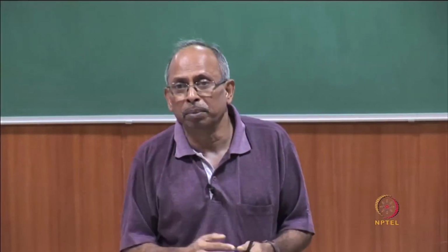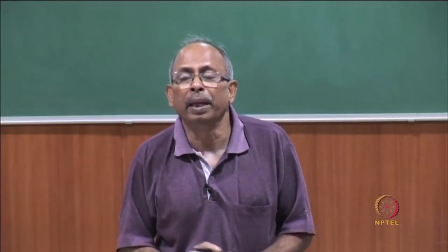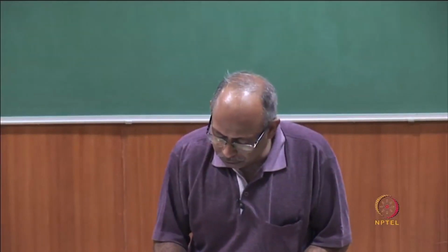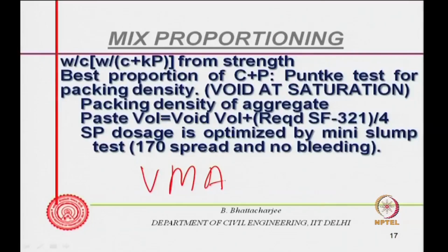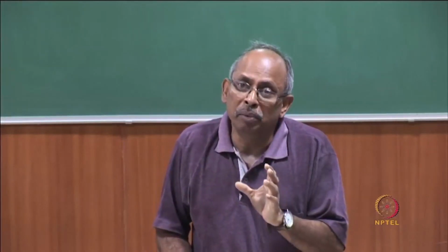Larger particle to larger particle, relative motion would be minimal while flowing. But supposing this is not happening, then you can use VMA, viscosity modifying agent, which we said would increase the stickiness, a kind of glue, and that is what we have seen for underwater concreting also.